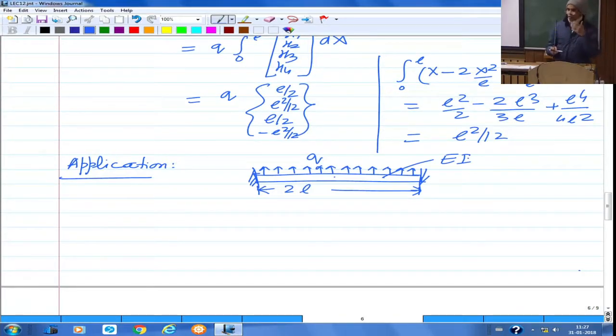So this is a beam under loading in one plane, so it will obviously undergo bending in one plane, and that is what we have derived right now, the element level stiffness matrix. Now to solve this problem using finite element, we first have to do discretization. You will have to think of how many elements. Suppose you discretize this into only one element. Because it is fixed at this end and fixed at that end, at fixed ends you will have V and dV by dx both 0. So although we know the actual beam is going to deflect, our one element solution will give everywhere 0 deflection and slope, and also strain and therefore stresses and everything. So we need to discretize this. One element solution is basically a 0 solution.